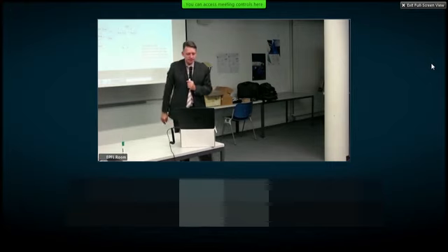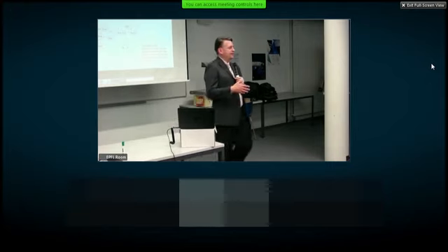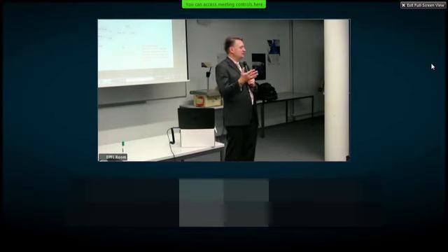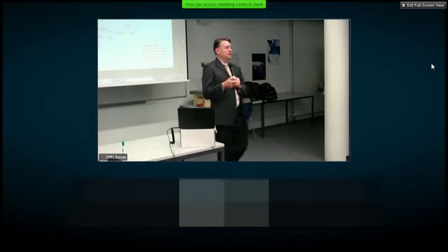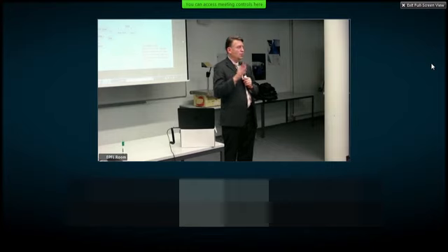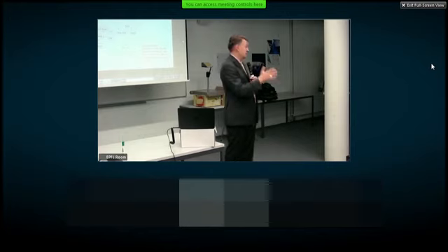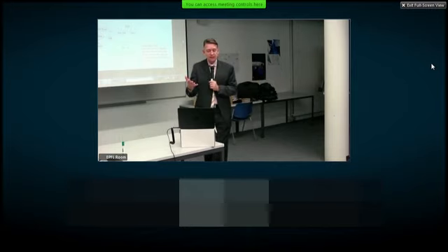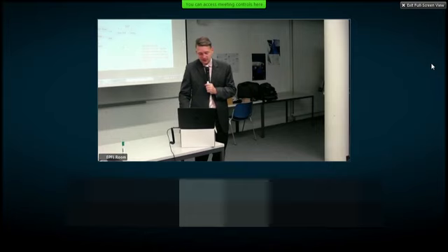One question that often comes up is, well, what if we have waste heat? There's heat losses and there are parasitic energy flows. Do we care about those? Do we represent those? And the answer is yes, you should, especially if they affect your performance or your requirements. The first thing you typically do as you map out your interfaces is map the flows that you want to happen, that need to happen, right? And then on top of that, you map out the flows that happen even though you didn't design for them, but you need to account for them. Heat losses would be an example of that, waste heat flux.